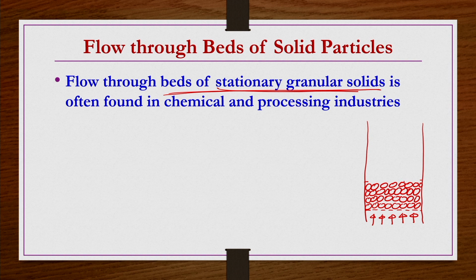If it is not closed at the top, sometimes the particles will rise and come to fluidizing conditions. Then the motion takes place in both phases, solid and liquid. Solids are floated and liquids are flowing at certain high velocities, right? These situations are usually known as the fluidized bed, which we will discuss after a couple of lectures. So let us restrict our discussion in this lecture only to the case of packed beds.